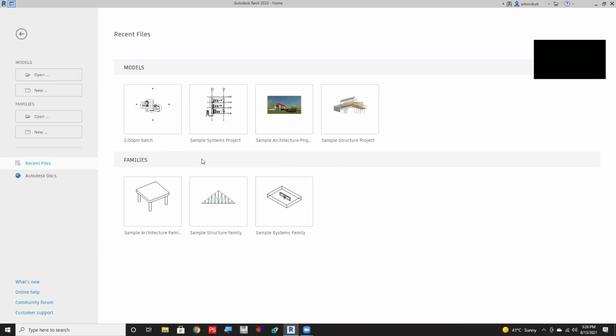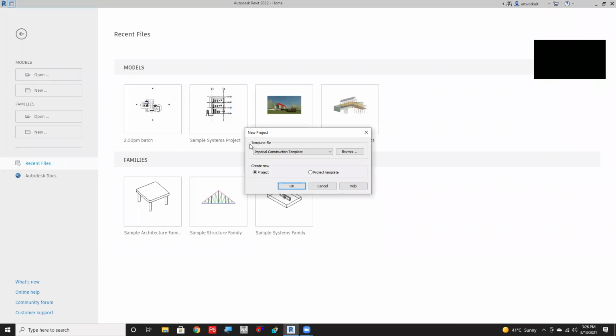Okay. So we were discussing automatic connection of ducting. Yes. Next, we are going to see the manual connection of ducting. So for that, here I'm going to this new tab, click on View, and I need to select this particular template. So go for Browse and click on Browse.